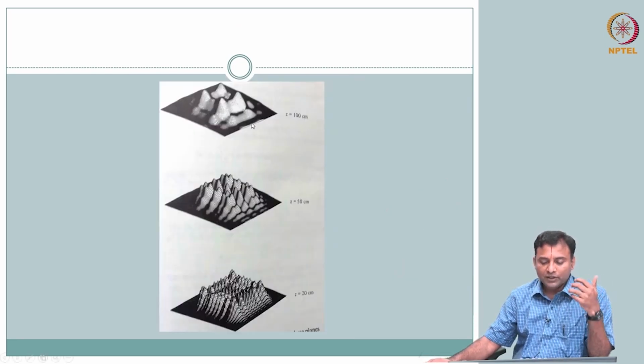So, what we will do is we will just quickly show some. This is from a rectangular transducer. What I showed before is circular, this is rectangular, and you see a similar trend in the near field. What is a near field or far field? Remember, go back, we just made some formulations, right? If it's a circular disk, d square by 4 lambda, so 2 times that, so d square by 2 lambda.